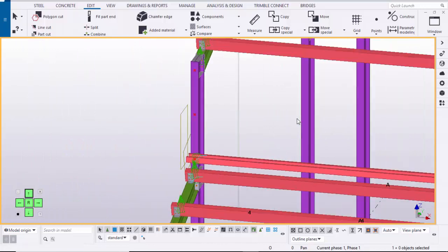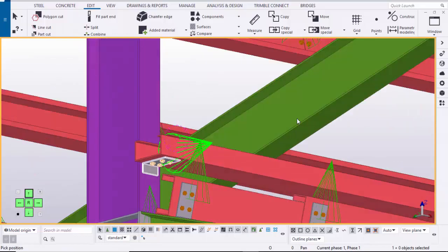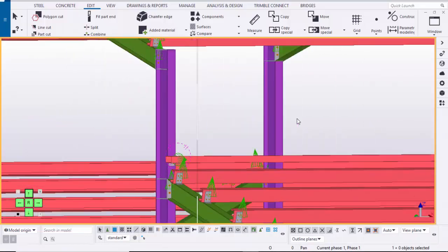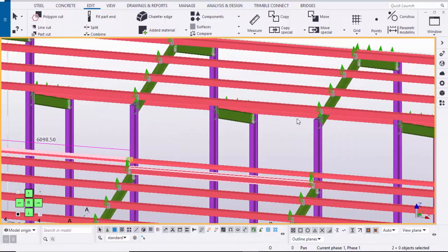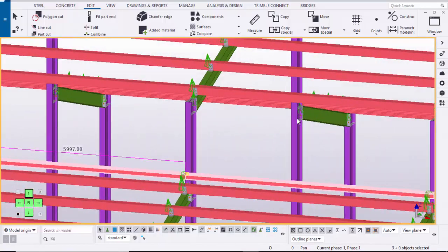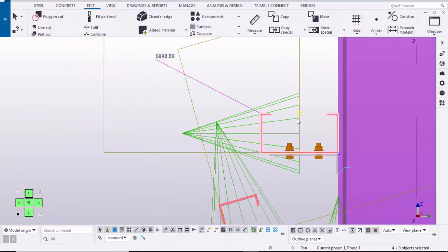That's it. Click on space, redraw. Now we have the connection here like this. Now we're going to copy these guts in two more points. So hold the control button and select this sidewall guts. Then go to elevation on grid A. Then right click on mouse, copy